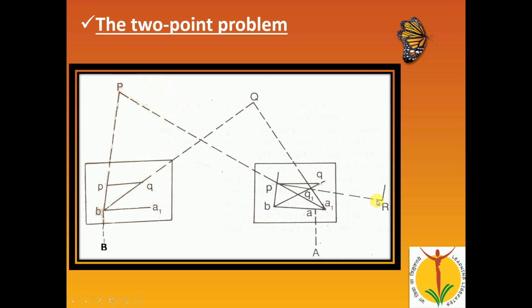In the next stage, we place the alidade touching points P and Q, and we move the table in a clockwise direction along with the telescope, and with the telescope we bisect the ranging rod R. If we move the telescope using the wing nut, this point A1 shifts somewhere here. When we move the table with the alidade placed at points P and Q, this triangular error is minimized, the position of point A shifts to here, and that point is the correct point.